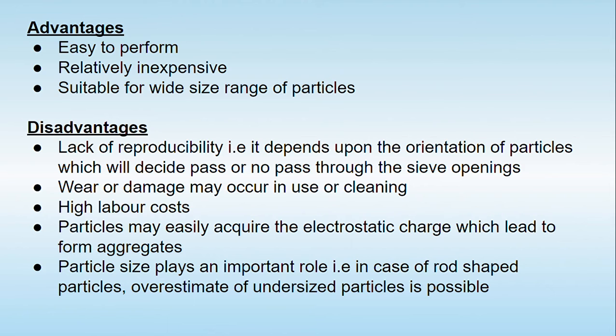It depends upon the orientation of the particles, which decides whether a particle will pass through the sieve opening or not. When particles come into contact with the sieve opening, the arrangement or orientation of the particle decides whether it will pass through. Another disadvantage is that wear and damage may occur in the course of cleaning, and there is higher labor cost.